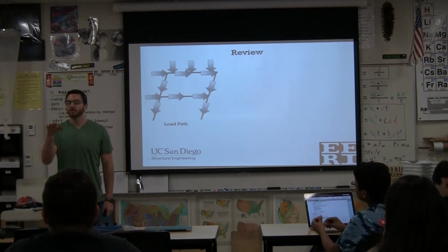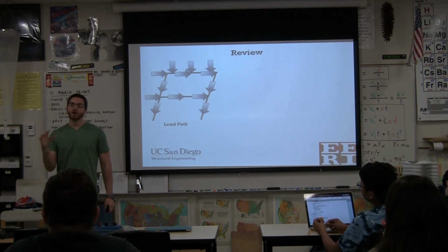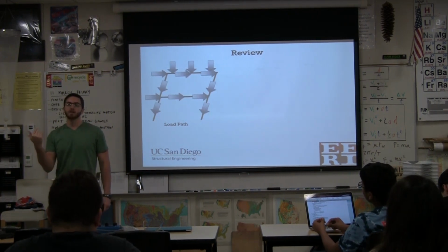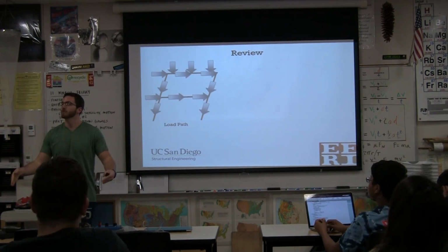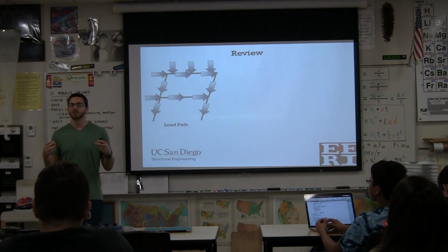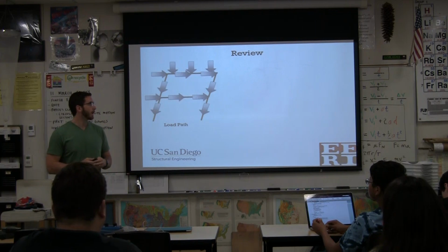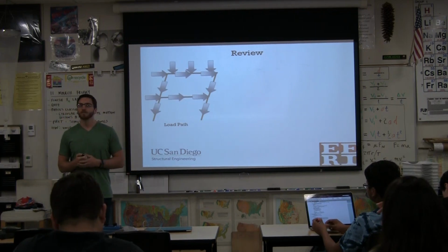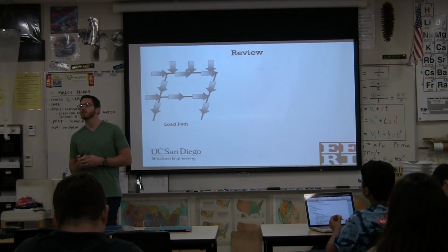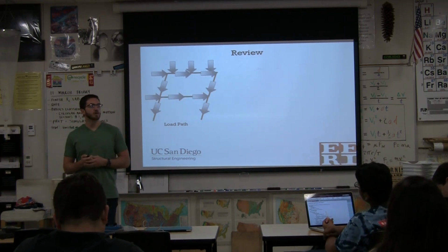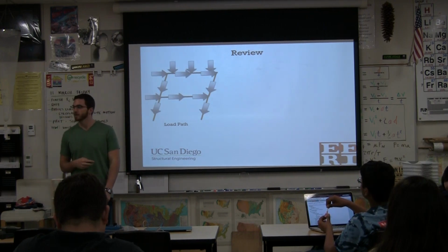The one thing I'll say, and my slide might have been a little confusing: there's still a horizontal demand, even just from dead load. The forces still have to go sideways and then down through the column. The idea is it's just much less than in the dynamic case when there's this horizontal load. Anything else about load path? Why is it important? The next little picture might actually help answer that.